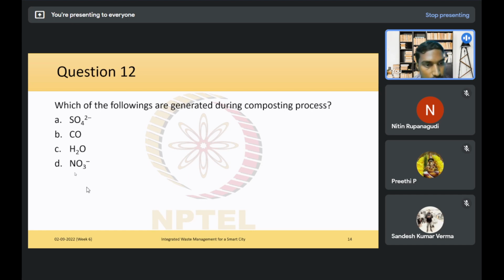Okay, there is a question in the chat. Do we consider the following for the biological treatment or not, like wood and rubber? So, as I said, they can be biologically treated. However, since they take a long time to degrade, we do not generally use them for the biological treatment because we have to wait for a long time, right? So that is not practically feasible for us, to wait for a long time for this to degrade and then use the end product. Therefore, we generally avoid wood and rubber, but they can be biologically degraded.